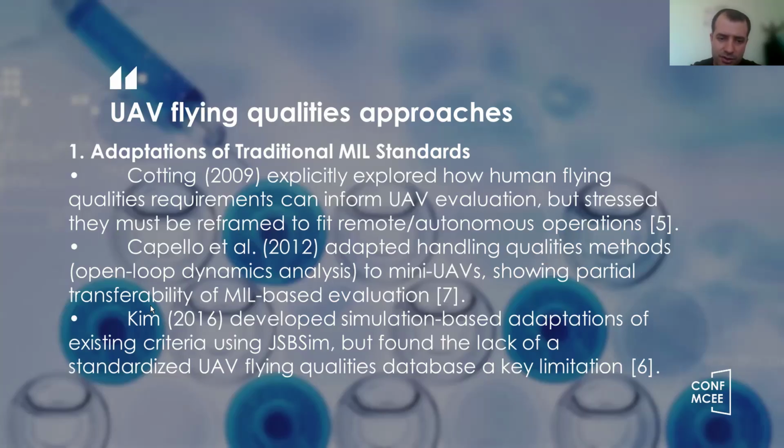These approaches use military-based stability, control, and response measures as a starting point, but adjust thresholds and interpretation since there is no onboard pilot. And they all mention the lack of a standardized UAV flight quality assessment method.